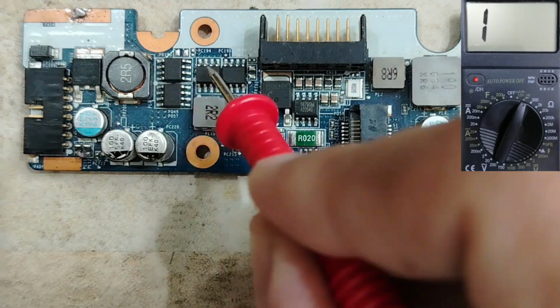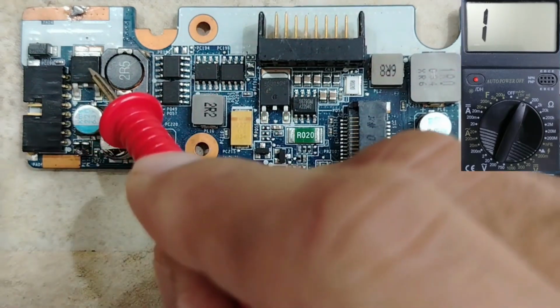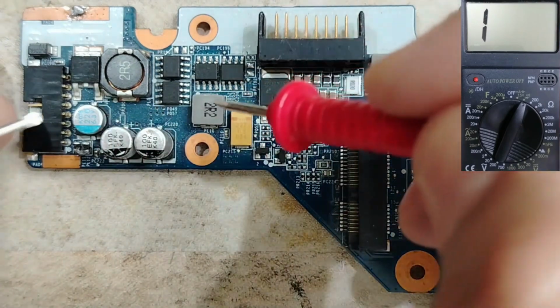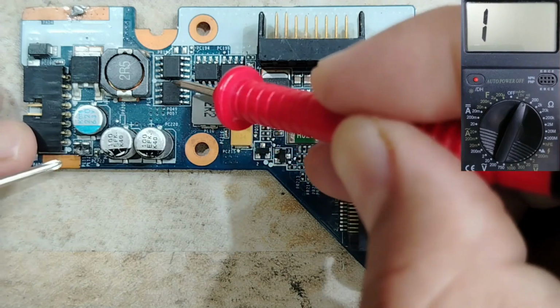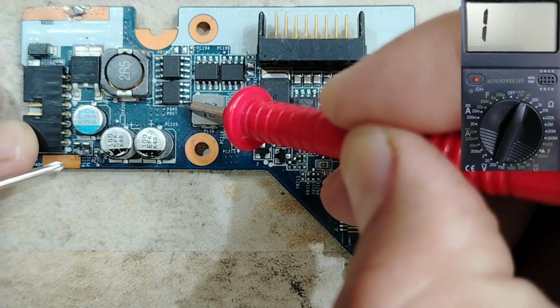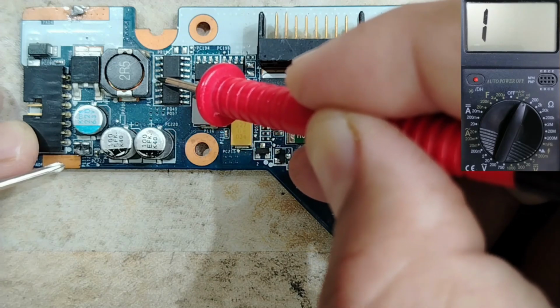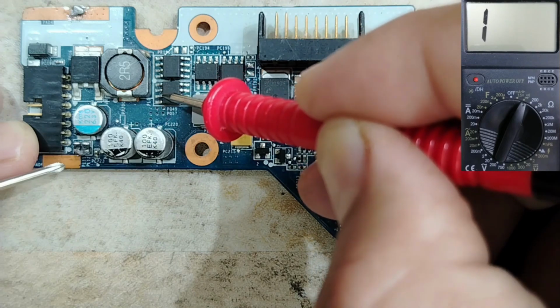Now let's move on to this kind of MOSFET. This is basically an 8-pin MOSFET, the same as a 3-terminal MOSFET. But here, as you can see, you should always locate pin number 1. Do you see here we have a small hole, or of course you can use this dot? Do you see this white dot? This white dot means this is pin number 1, pin number 2, pin number 3.